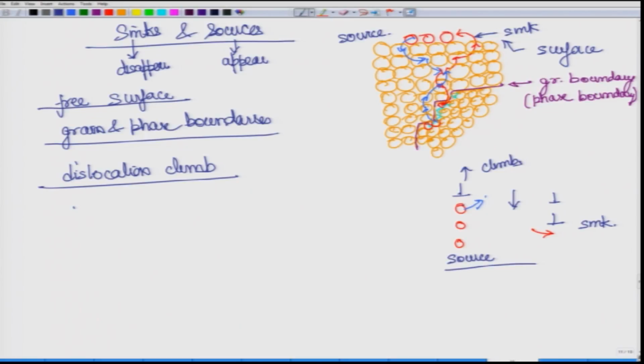Still another one is vacancy disks. Inside a material you can have a disk made out of basically empty atoms. So, there is a region where there are no more atoms, while around it is still all atoms. I am just trying to give you a rough scheme of things. It is just that there is a missing atom over here. So, this is like a vacancy disk.